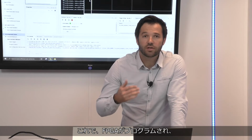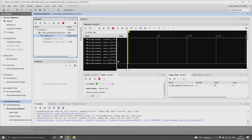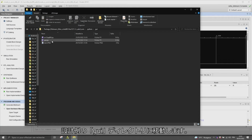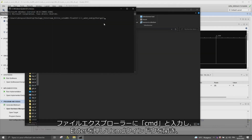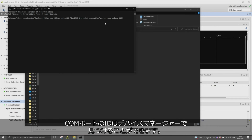Now the FPGA is programmed, we can open a graphical user interface. Go to the Design Example Graphical User Interface directory. Open a command window and type python GUI.py COM plus the ID of the COM port. You can find the ID of the COM port in the device manager.